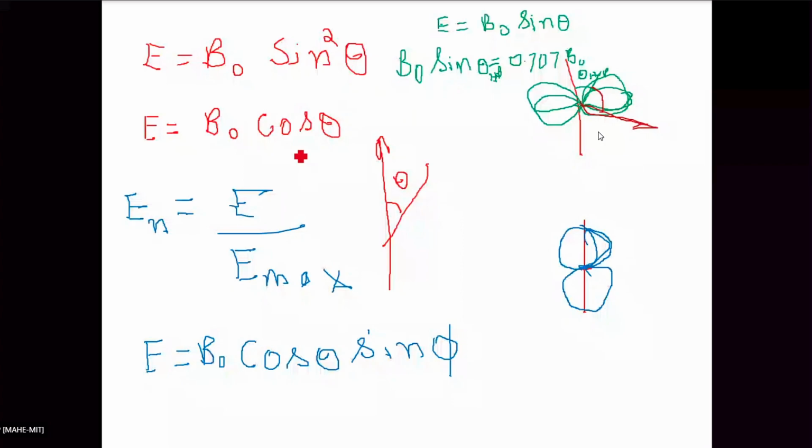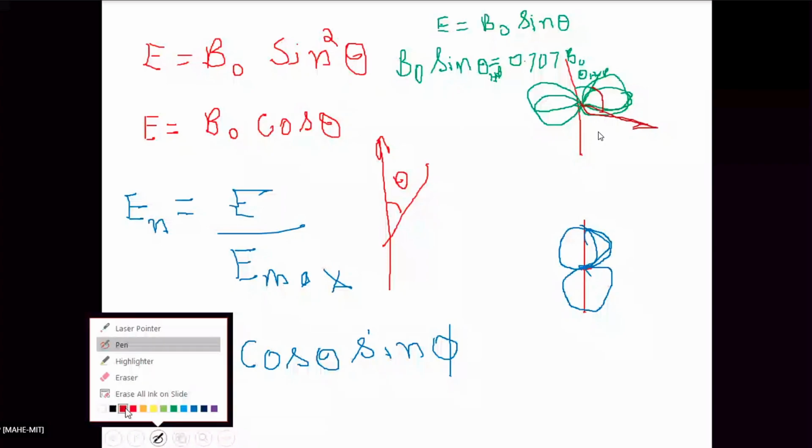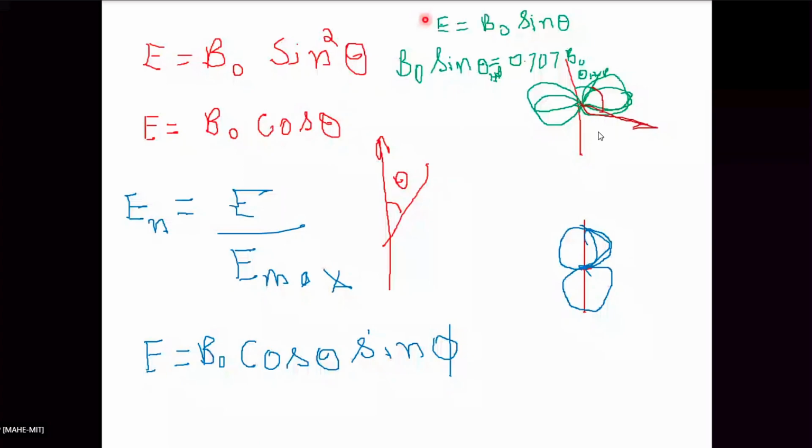See, theta HP, one of the points is 45 degrees. Sin theta is there. What are the half power points? One is 45 degrees. Yes, sir. See, this is the 45 degree angle. This pattern is like a circle, no? On the other side there is also a half power point. What is that? 135 degrees, this angle. Do you get it? 45 and 135.